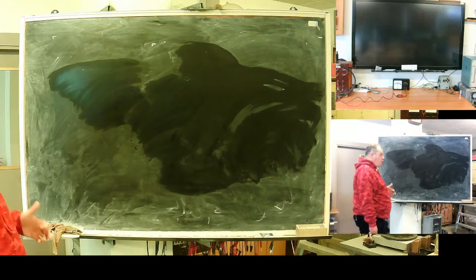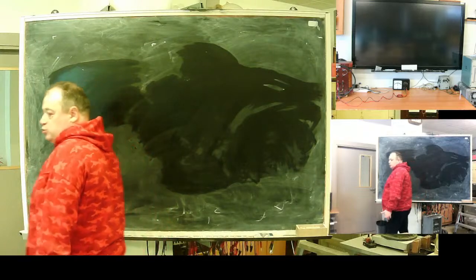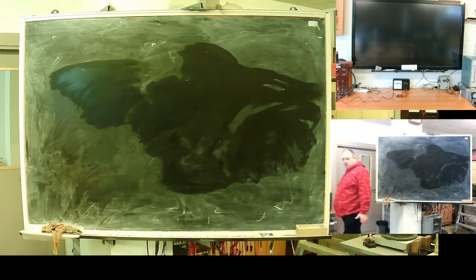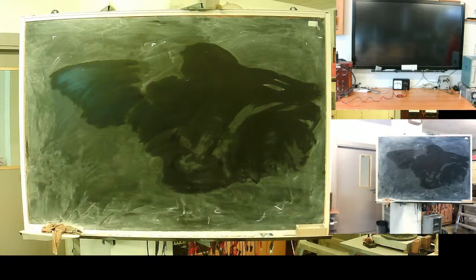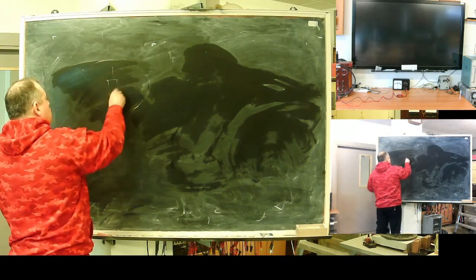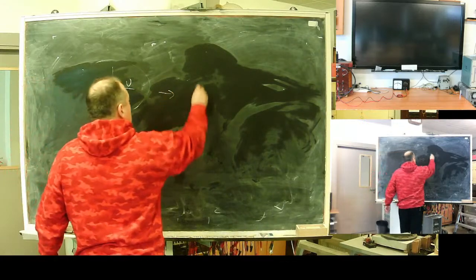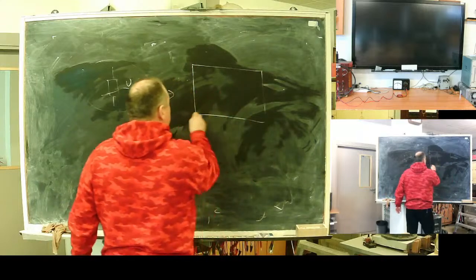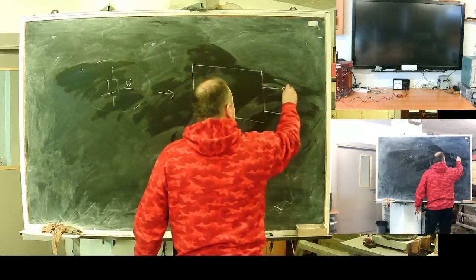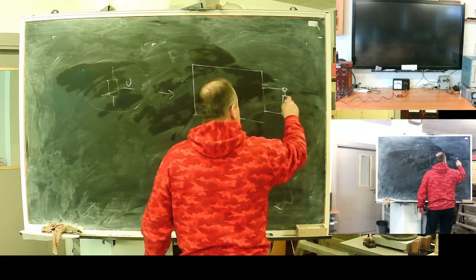It can be worked around by separating the network into linear and non-linear parts. We can perform the solution in symmetrical components on the linear part. So, a network with a non-linear element should be converted into a multipole network, and here non-linearity should be separated.